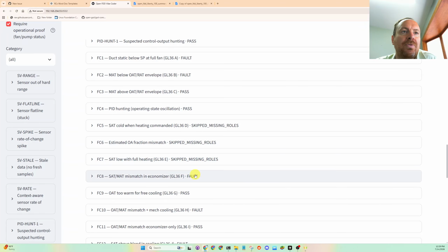So this air handling unit was just, if you remember the pictures from yesterday, a variable volume air handling unit with a cooling coil, and it's a mixing air unit. So just a traditional supply return fan, variable volume, duct static pressure control with one cooling coil, no heating coil, and an economizer.